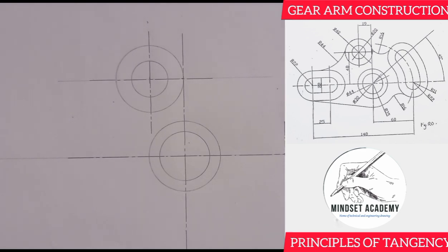So the next thing that we're about to do here is the radius of this outer arc here is given to be 22. So this is radius. You see the arrow in front of it, so you're not dividing it. So use the 22 directly, as you can see it there, and the 11 too, and draw two semicircles.